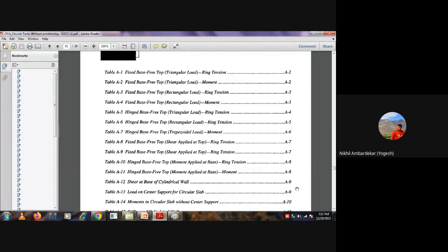100. So that 100 kilonewton moment, from 100 it will be somewhere reduced to 50 at somewhere midpoint, and again the remaining 50 will be generated at the base of the slab. So if you just make it additional, it will remain the same, because ultimately why is it coming? Because of water pressure or soil pressure. We are not reducing that. Correct.